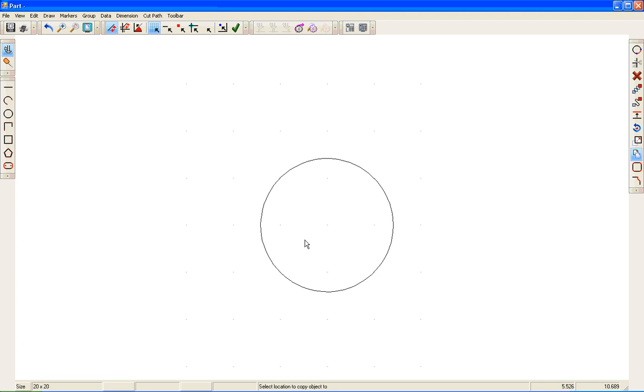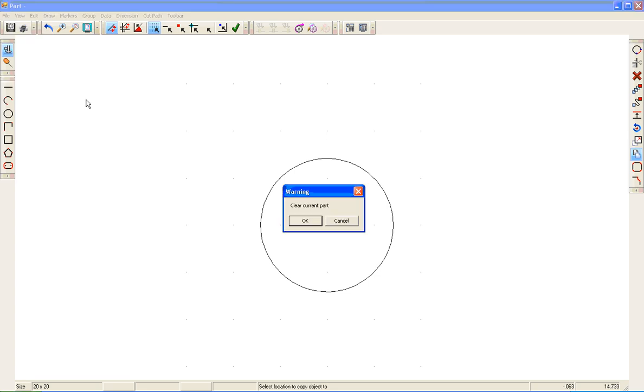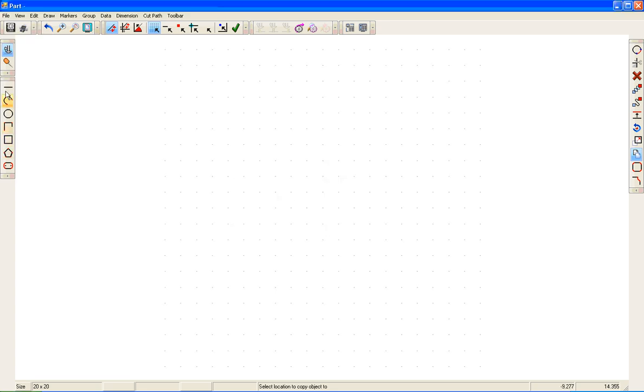Actually, I'll go ahead and just show you real quick. Okay, when drawing a line, it can be very hard to draw a straight line, depending on which input method you're in. If you hold the Shift key down, it's going to give you a nice straight line in all four directions. Okay? If you hold the Control key down, it's going to give you a 45-degree line in all four directions.